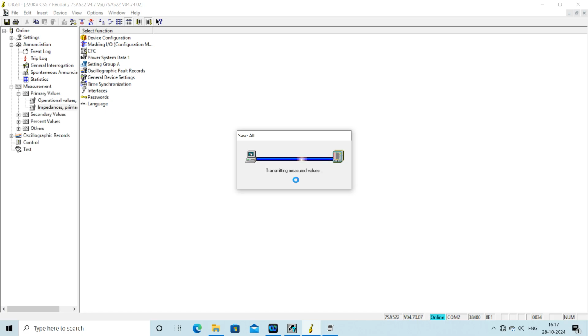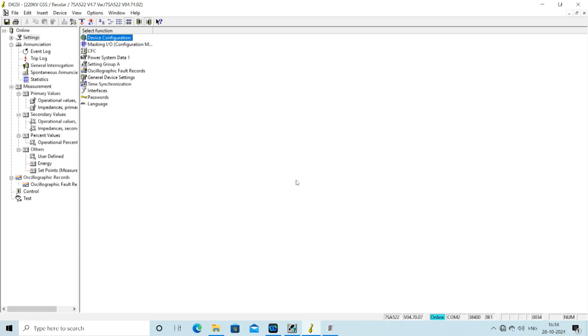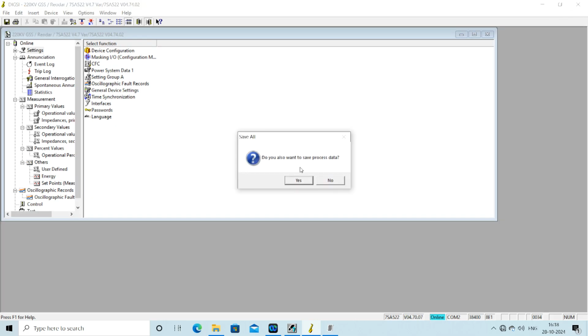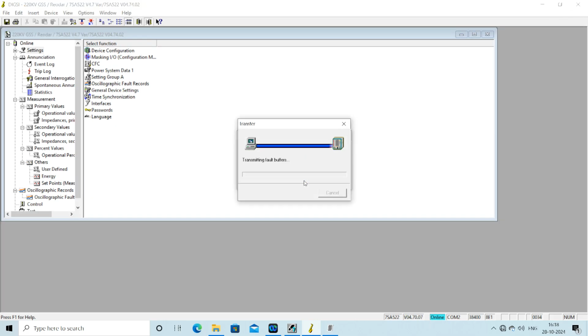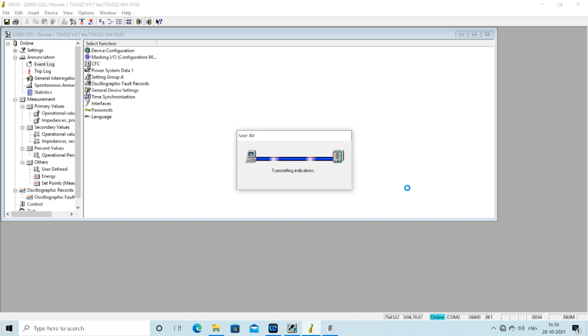Now most of the Siprotec relays have the same port configuration and can be communicated in the same way. Some of the relays of the Siprotec family also have USB connections, which are communicated on the front port instead of this serial communication. Relays such as the 7SJ group have those USB ports. I will also make some videos on those relays.